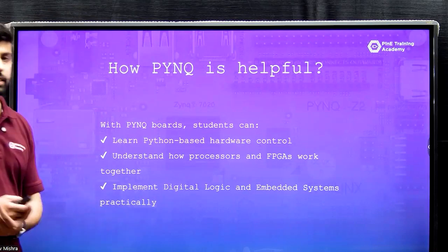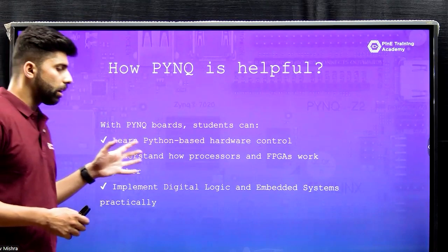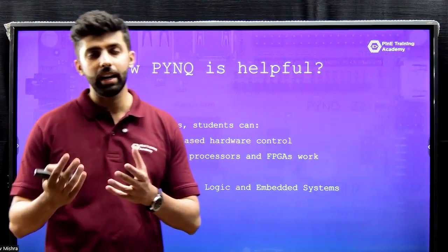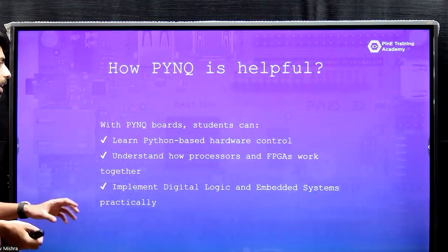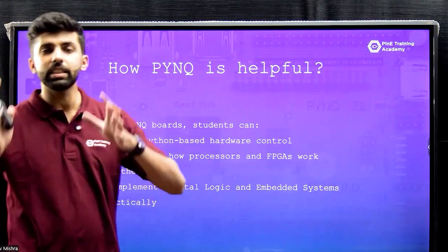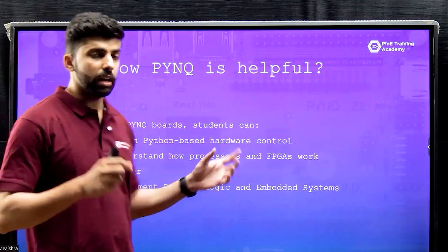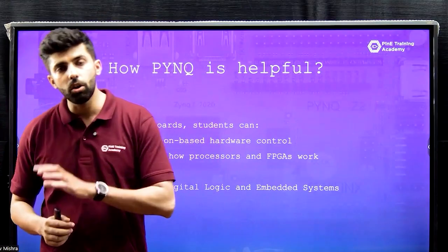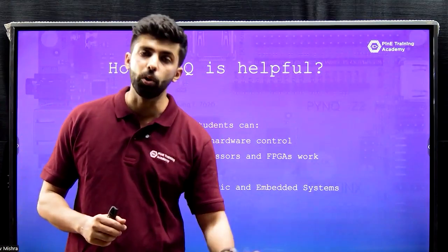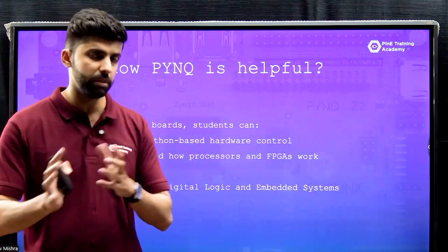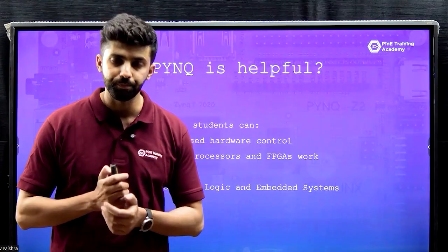Now, how is PYNQ helpful? So you can learn how to control hardware using Python, and Python is again very simple. And you can understand how processors and FPGA work together, right? You can implement all the digital logic on this PYNQ board. Like you would do with the help of VHDL, you can do the same thing with the help of Python.